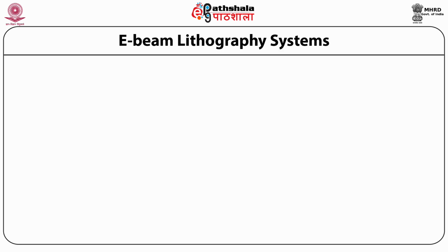The most important advantage of the E-beam technique over standard photolithography is that it can draw patterns with nanometer resolutions. E-beam is a maskless technique which has high resolution and low throughput. As a result, its use is limited to fabricating photomasks, producing semiconductor devices in low volumes, and research and development activities. We will now discuss the electron beam lithography systems.